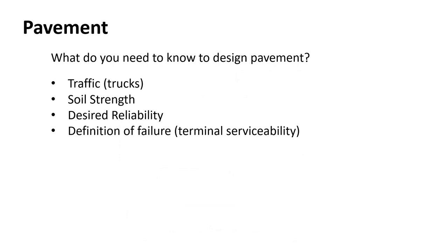If you're going to design pavement, what do you have to keep in mind? You've got to know trucks. What about cars? We don't care about cars. Cars do nothing to pavement unless that's all that's driving on it. Then you would care about it. But if you've got more than 1% trucks on a road, all you care about is trucks generally. And that's any state highway, any major, even collectors, arterials, interstates, all of that. The only thing you care about is trucks. The cars do almost no damage to the pavement. It's all the truck traffic. And we're going to see that here in a second. If you remember from last year, you'll remember that truth.